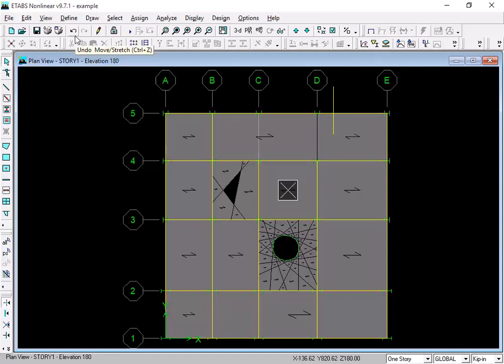I think you can either undo or go back there and plug negative values for delta and it should come back. No, it's not 0, 0. It is not ordinate. It is delta. For the global axis that was ordinate, but for this it is delta. Delta means difference between initial and the final. So plug minus 50 and minus 80 and it will come back.